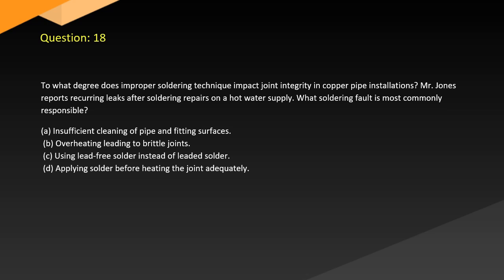Question 18. To what degree does improper soldering technique impact joint integrity in copper pipe installations? Mr. Jones reports recurring leaks after soldering repairs on a hot water supply. What soldering fault is most commonly responsible? A. Insufficient cleaning of pipe and fitting surfaces.